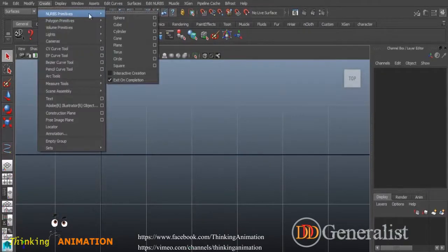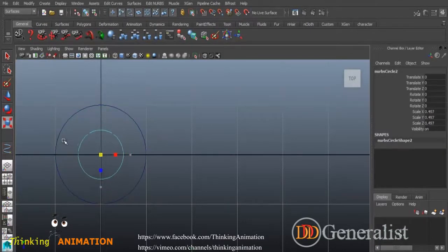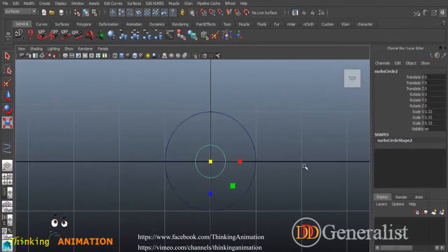Okay, if you select here, you create a circle. Now I'm going to duplicate this circle and create this smaller one. And now what I'm going to do is select this line, turn on the snap to curve option, and select the Z, press here, and you have it snapped here. Ctrl D, same, you snap it here, and now Ctrl D, you turn it off, bring this here right in the center, select the x-axis now, turn this on, with the middle mouse button click here, Ctrl D, and you have the points like here.